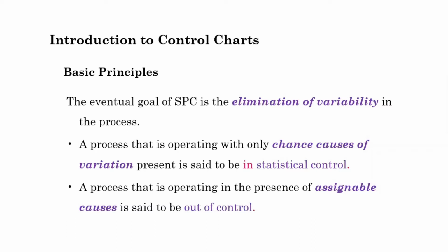Or if the operator does not really take care in measuring the part to be cut, then we might have variation. For example, if they are negligent, they might not even take the proper measurement instrument to measure what is going to be cut, but rather they would just estimate and cut it. Or they will not place the measurement instrument properly. They might incline it, or they might do it in a negligent way that would result in a dimension of maybe 9 centimeter or 11 centimeter or whatever. So these types of variations, we can say that this is an assignable variation.